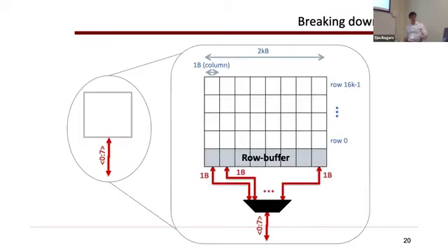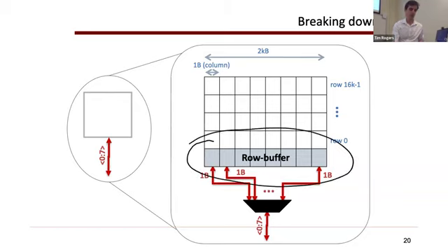Okay. And then inside each individual bank, of course, there's these things called row buffers. And when we read stuff out, we get much more data than maybe we wanted. And in this example, we're showing 1 byte per column that should read out, and then you switch to select which of those bytes you want in the column mux. Okay, and the row buffer, like I said before, this could just be implemented as there are sense amps in all of these.